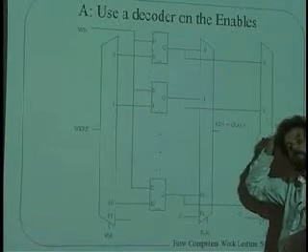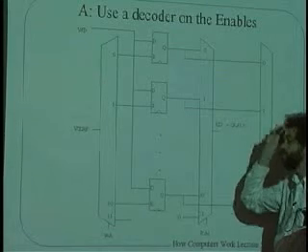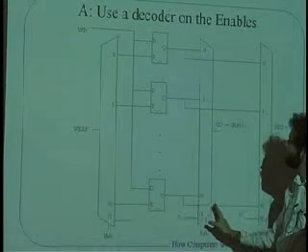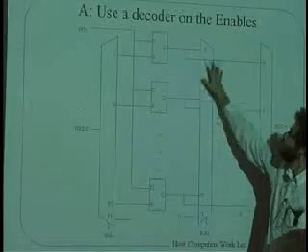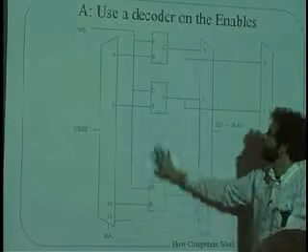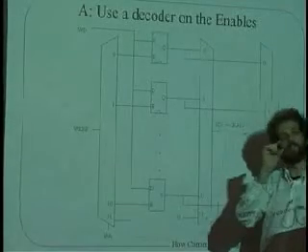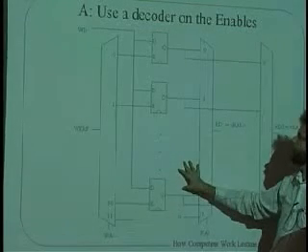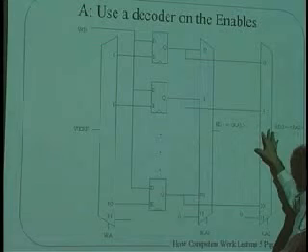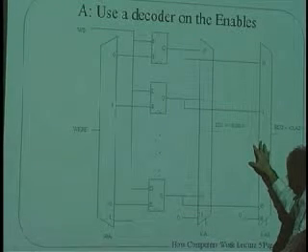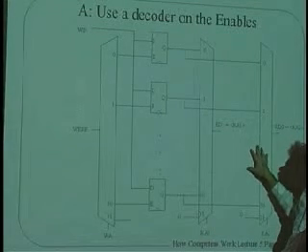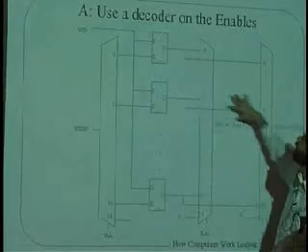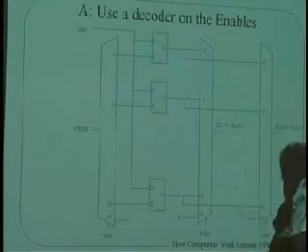A typical register file back in the 1970s, 1980s was built as a single chip with this multiplexer and the registers all inside of one integrated circuit. And the question was, if you had such a thing and you wanted to add another read port to it, how could you do it? And the answer was it became too difficult to do because there were so many wires that crisscrossed across the entire chip that it became very, very hard.